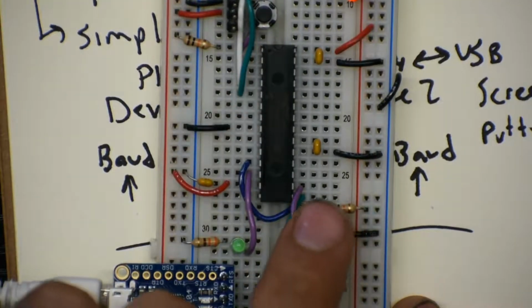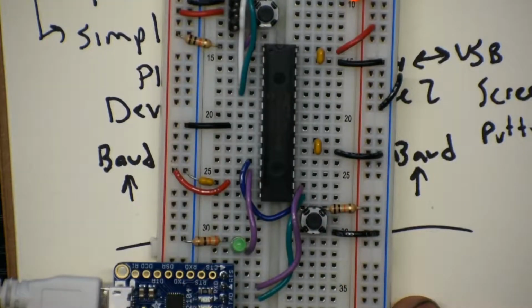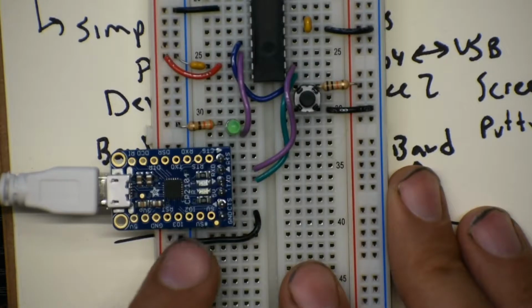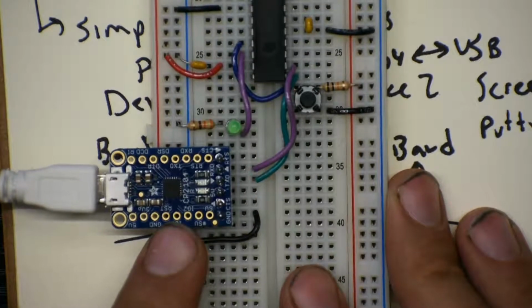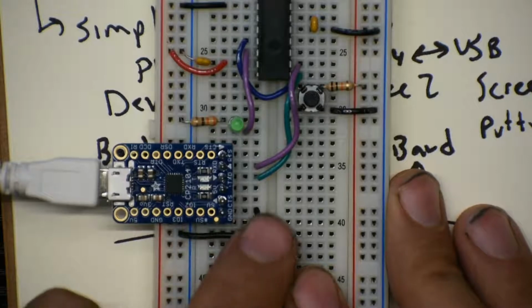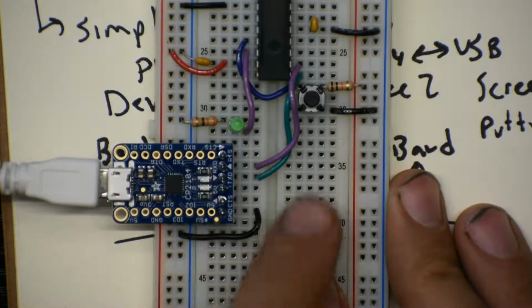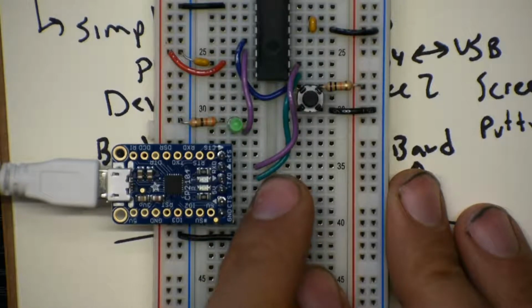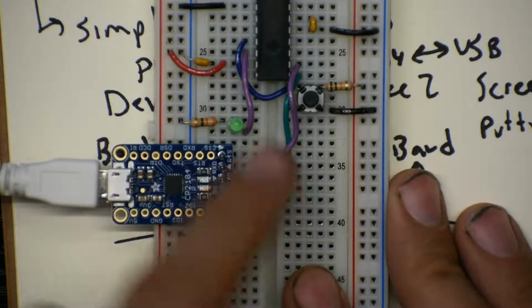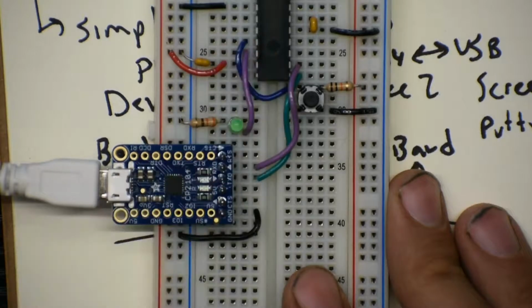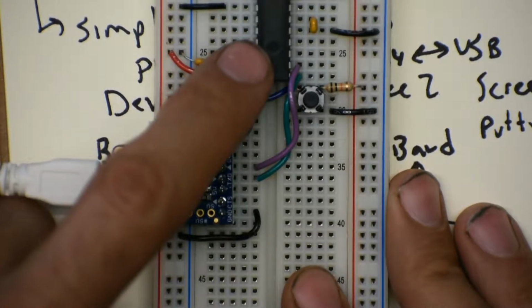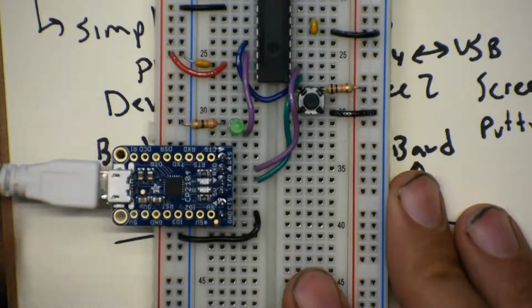So right now there's no clock, so it won't run. Let's switch over that code so that it runs with the internal oscillator, and then let's add in the USB to UART chip. So notice the connections that need to be made. We have a ground connection because we need common ground. And then we have 2 pins, TX and RX, from the Friend board that need to be connected to 2 pins on the PIC. So we need to figure out what pins we connect to on the PIC and how we turn those on in the UART peripheral and assign the pins and that kind of stuff.